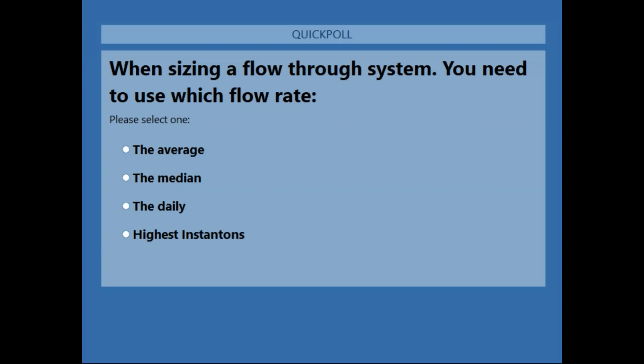So, looking at a fairly standard pH system design here, 78 GPM, 20-minute residence time, 1,560 gallons total volume. We have 2 800-gallon treatment tanks. From a graphic standpoint here, these are our 2 treatment tanks. This is our reagent injection. That's our bicarbonate injection, P and ID. This is our acid and base, bicarbonate, and our 2 treatment tanks. So that's how you would, in a relatively simple sense, size a system based on a not particularly complicated waste profile, looking at it more from a flow profile perspective.